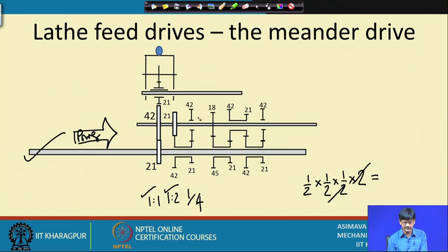So, that we have just left there. In addition, if we extend it to get those ratios of 5:1, 10:1, etc., we can employ these two gears. How come this center distance is accommodating two different gears? Because the sum of the teeth must be the same. 42 plus 21 is 63, and 18 plus 45 will also be 63.